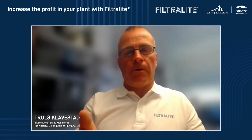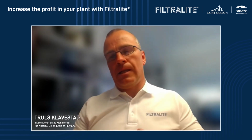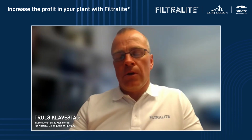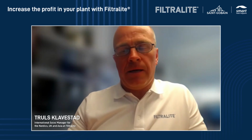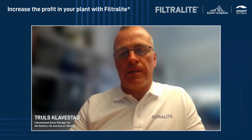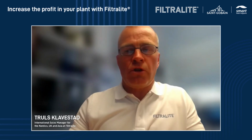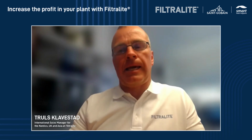We didn't talk about that at all today, but we have some brochures and things I can send to you. So in this case, when you have arsenic, you have two options: activated carbon, or Filtralite HMR that you can use. I can also connect you with my colleague in R&D, who has been working a lot with this HMR product. He's a specialist on that specific product and what we are able to do. But traditional Filtralite, used for drinking water plants, I will not recommend for that case.